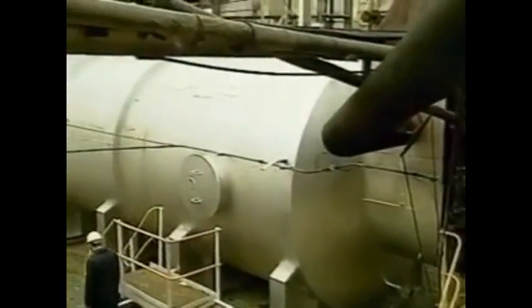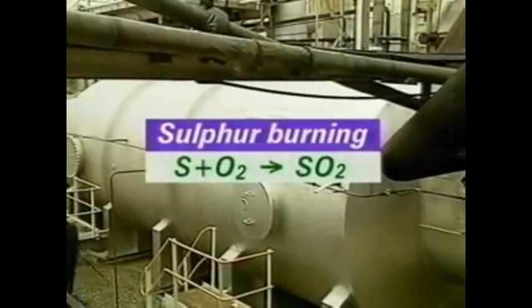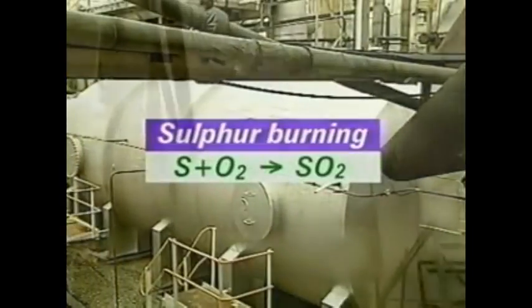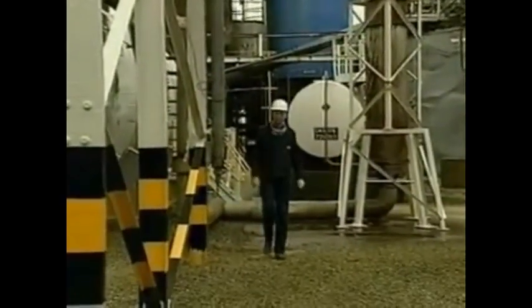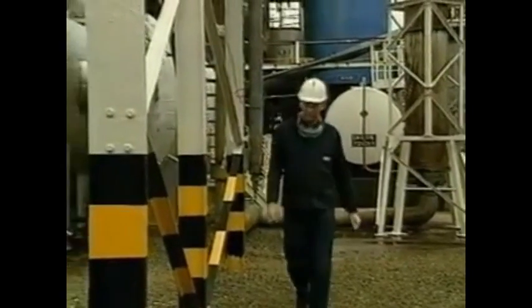Sulfur combines with oxygen in the air to form sulfur dioxide. The oxidation produces large amounts of heat. That heat is used to boil water to produce steam to generate electricity. The gas mixture, which leaves the furnace, contains sulfur dioxide and enough oxygen for the next stage.